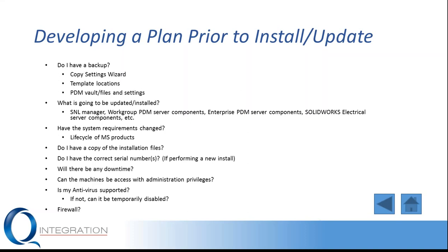Because if we're overriding any of these, if we encounter any troubles during this installer update, we may not have anything to fall back on, and that can be pretty devastating to a company. So we can utilize things like Copy Settings Wizard to take a copy of our user settings on the client machines. We can copy those template locations, place them in a different directory as just a backup, and there's also tools in place to create backups for our PDM vault, as well as the files and the settings.